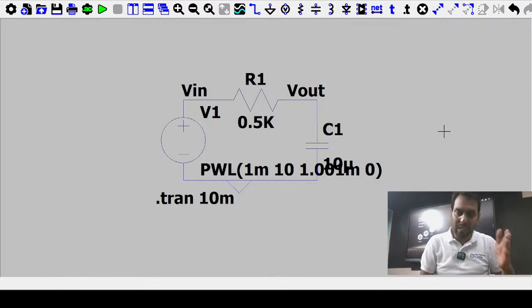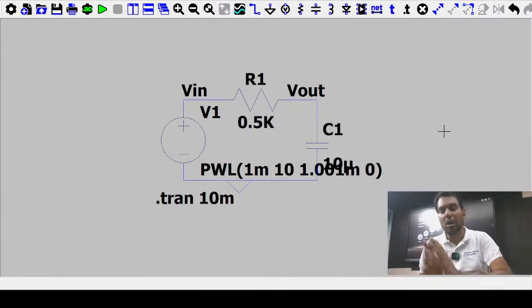Till now we were talking about rising or falling. Now I am making the input voltage such that in this waveform you have the input rising and also falling. It behaves like a duty cycle, and in the first phase I am thinking that the pulse width is very far away from the time constant. Let me make this time constant 1 micro.